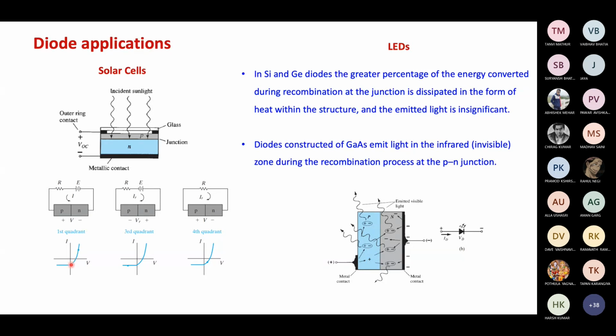And that's why this plot starts from a negative value. And as we apply a positive voltage, first this current becomes 0 and then it becomes a positive value. Okay, so this is the IV characteristics of a diode in presence of light. Please remember this. This is also very important, especially in optical devices, optical diodes, solar cells especially, and photodiodes